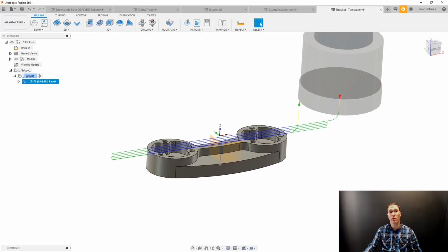Now, I would want to go and do this for all the toolpaths I need. If you remember in the original file, I had like 10 operations that I was using. So I would probably, well, definitely, I would put in all operations here. And the benefit is that I have one file that has all my operations, and it also has all of the other bodies or components and stuff for manufacturing.